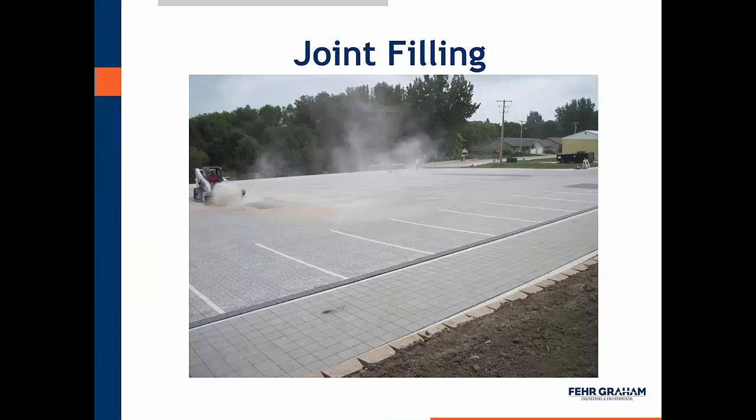And here at the end of the project, after the pavers are placed, then we fill those joints between the pavers with, again, the same 3/8" chips that were used as the setting bed. And those are just scattered out loosely on top of the pavers, and then the contractor will go through with a large rotary broom, which you can see in operation here, and just work those chips into the joints.